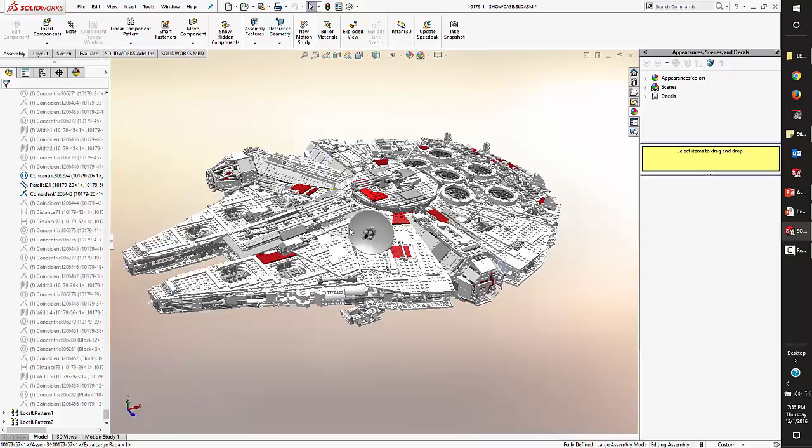Now, if you change 18 parts, you have to do that 18 times. Make sense? Let's say that takes 2 minutes per part per change. So now we're up to 36 minutes of work. If I open this up, and I've tried it one time, I got to about an hour and 10 minutes, and I gave up and shut down SolidWorks. So I've never actually loaded this fully resolved, but I know it takes longer than an hour. So do I spend that hour opening this up full weight with the mates calculating, or do I take the 36 minutes to go through and manually make the change?